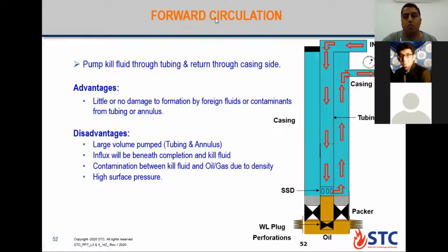Last disadvantage. Mr. Ahmed, yeah, the DHSV would be our secondary barrier as well. Downhole safety valve, DHSV, okay. Would it be our secondary barrier or our tertiary barrier? Usually, as we said before, according to the API, the downhole safety valve is an emergency barrier for production only.